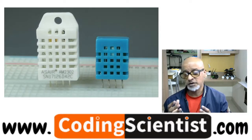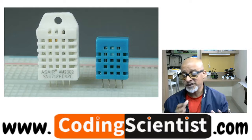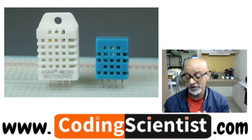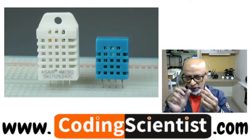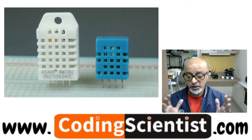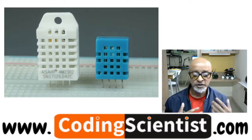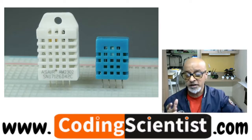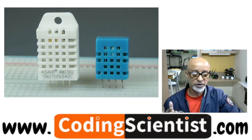I'll show you the table which compares them. Basically, I'm going to show it to you in the next slide, some of the most important specifications of the DHT11 and DHT22 temperature and humidity sensors. These sensors contain a tiny little chip inside the blue or the white casing that basically does the analog to digital conversion and spits out a digital signal with the temperature and humidity of the environment, right? This makes them very easy to use with any kind of microcontroller, not just with ESP32, but you can use it with Arduino, Raspberry Pi, any of the microcontrollers, right?